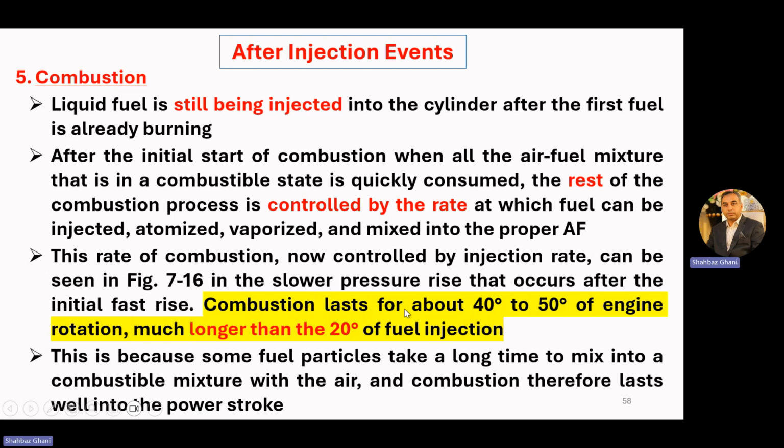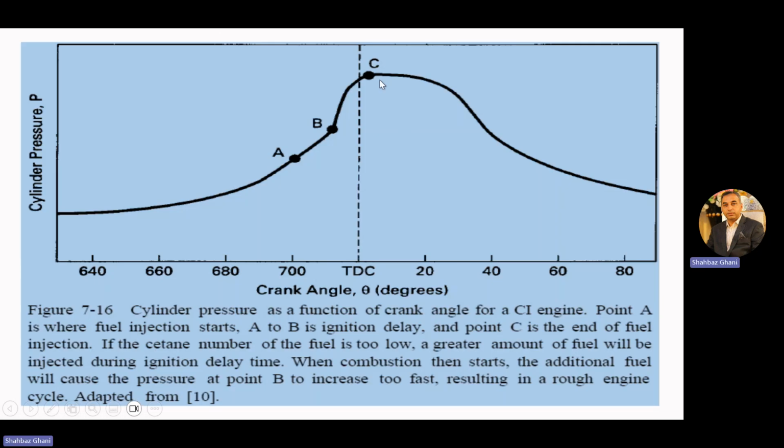Combustion lasts for about 40 to 50 degrees of the engine rotation, much longer than the 20 degrees of fuel injection. Up to point C, fuel injection stops, but this is at 5 degrees after TDC. The combustion will remain for 40 to 50 degrees after this point.